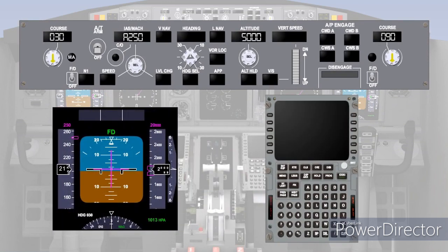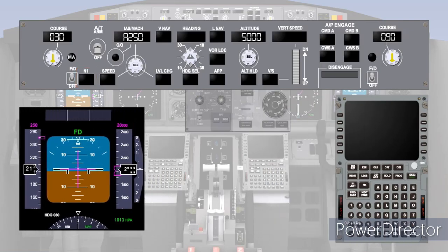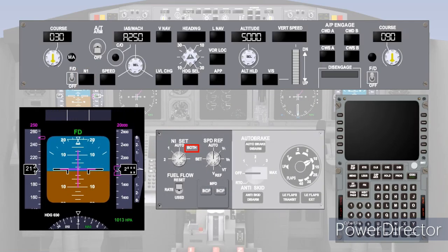The flight management system can also command a speed target. The thrust target could be a value of N1 or engine pressure ratio, EPR, depending upon which has been designated the primary thrust setting parameter for that particular engine. The target thrust can be set manually by the pilot, or it can be calculated by the thrust computer based on standard thrust ratings for takeoff, climb, cruise, go-around, or continuous.